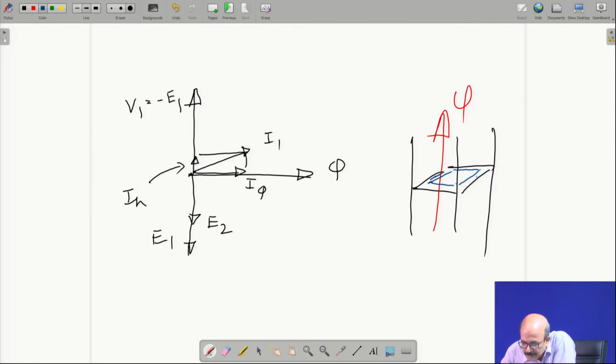Suppose I arbitrarily put this current and this current, then it is the same direction. You can clearly see that's the same direction, so it has to be opposite, or the flux has to be reversed. So you can clearly see that the current direction will be this and this. The original one is wrong, and this current will always be looping. And then you can have n number of such loops, and the current will be flowing. Losses will be there. So that is eddy current loss.